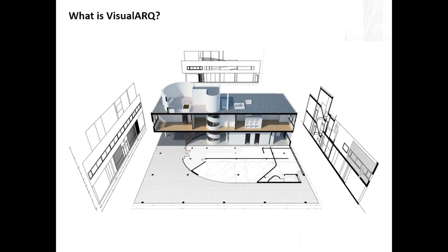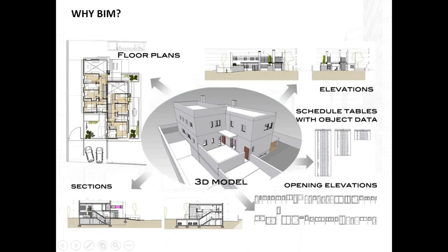VisualARQ, as you may know, is a plugin for BIM that works on top of Rhino and improves the process of modeling architecture inside Rhino, not only for generating the 3D model, but also for generating all the 2D documentation. We say that VisualARQ adds BIM features to Rhino because all the documentation is generated from the 3D model, such as the plan, elevation, sections, schedule tables, right? And so anything that changes on the 3D model then later on updates automatically to all the documentation that is generated from it.